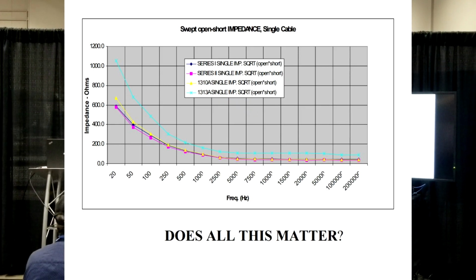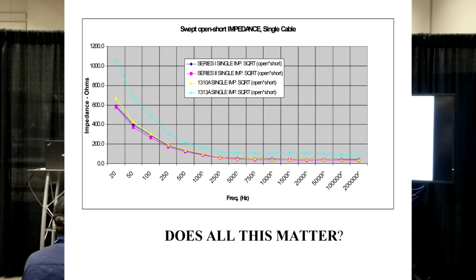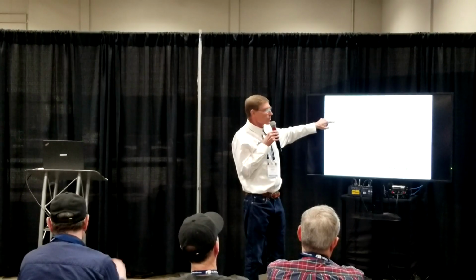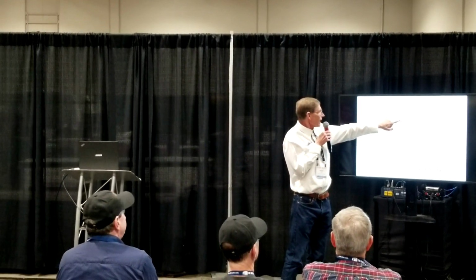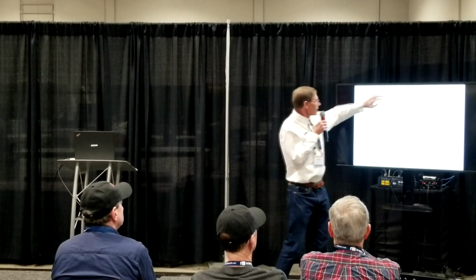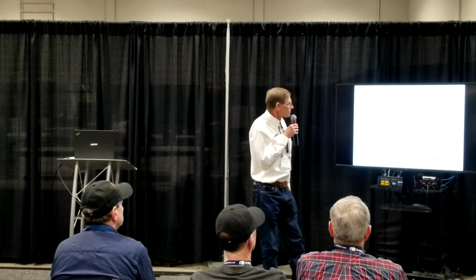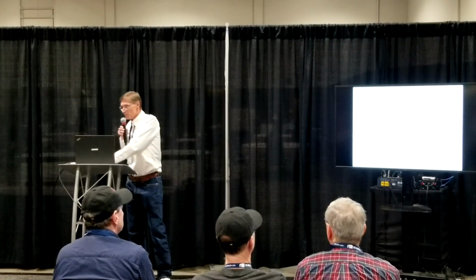This is an improved zip cord that's wired star quad, and if you wire it in a star quad configuration, I can drop the impedance significantly. So we've done some design changes at Blue Jeans to try to improve this low frequency difference. And then we have some Series 1, Series 2 impedances on there. But there are differences in these cables. They definitely are not the same.